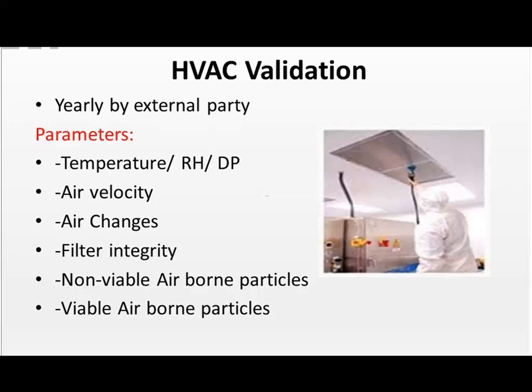It's important when you're establishing your environmental monitoring program that your HVAC system is validated, and it needs to be revalidated or recertified yearly by an external party, the one that has put the HVAC system in. There are tests that they're going to do to classify and qualify the HVAC system, and they need to come back yearly and requalify that system.